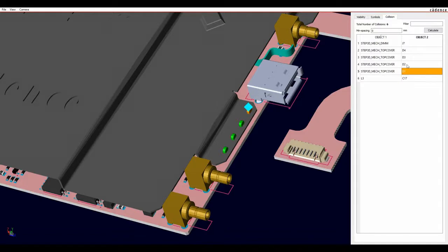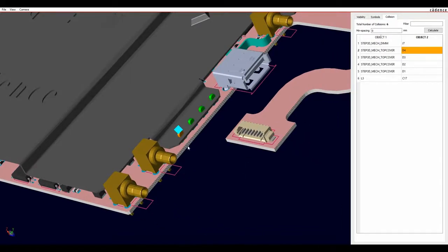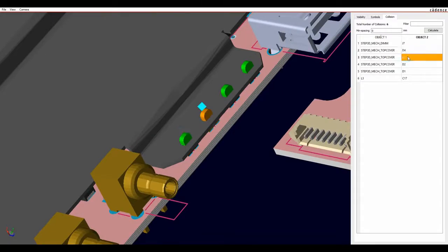I start to get an indication. So when I select what the components are, I can obviously select the cover, and it would highlight. I can select the individual diodes here, or the LEDs. I get a blue diamond to show me which component is effectively clashing, or what the issue is. It changes colour. So obviously we select a different LED. You can see I get the colour change. And even if I can't see it after that, I can use the right mouse button, locate, and the component will flash 5 times to give me an indication that there's an issue with this part. And you can see that the cutout inside the cover hasn't been created properly, so I need to go back to the mechanical engineer and say, you need to give me a new cover.